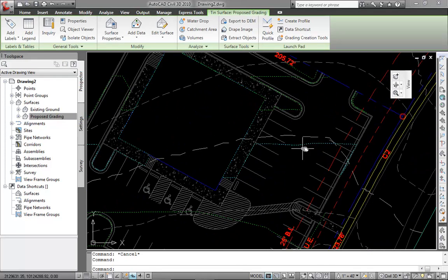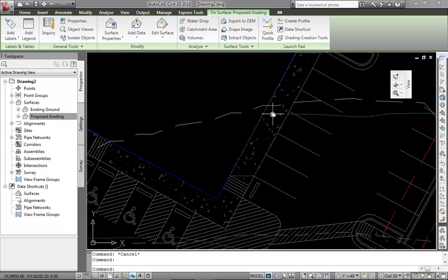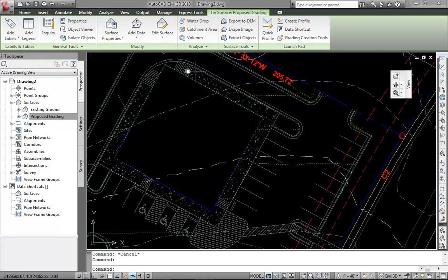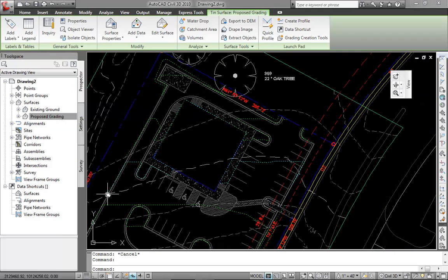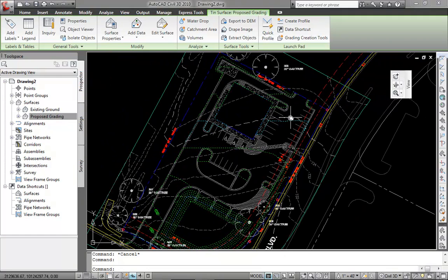And so as you can see, when you have a contour line, it starts at the existing ground and then it runs along the curb, comes across the parking lot. It's always finding its level line of elevation until it gets all the way around the building, and then it comes out this side and exits and ties to the other side. So this was all that one same contour elevation. So it almost follows the path of the existing ground, but until it gets to the proposed geometry of the building, then it goes around it, then around, and then back and ties in. Okay? So don't forget to change the styles when you add your labels.